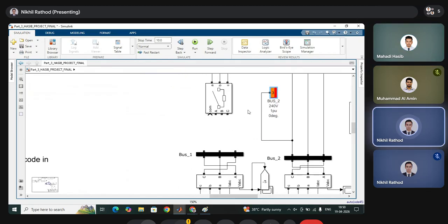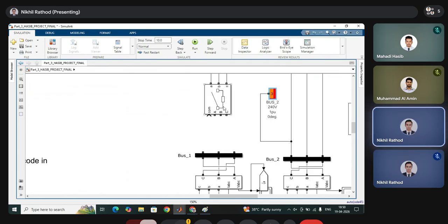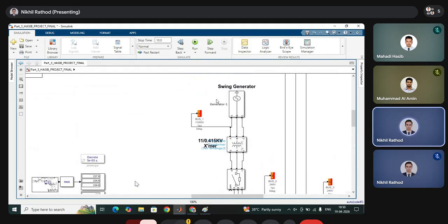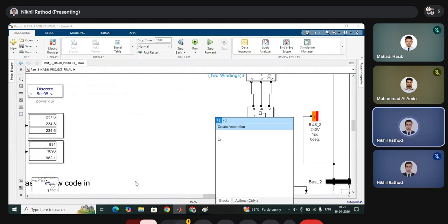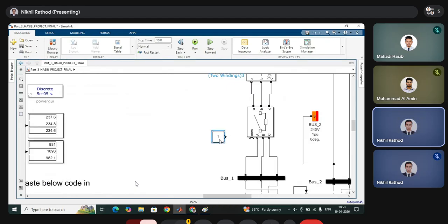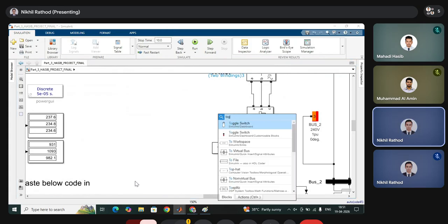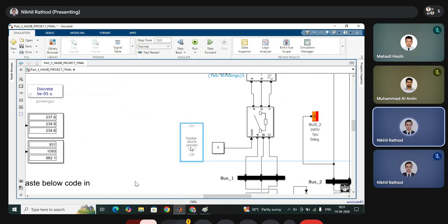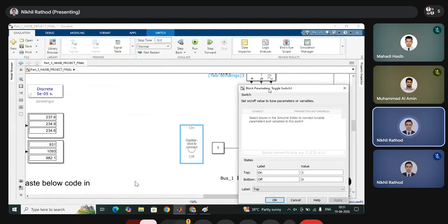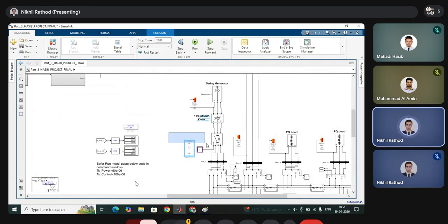But if you isolate this grid, because every generator is trying to, I can very frankly say, maintain frequency and all things through this source. It's a swing source. And if you directly isolate it, that may cause instability inside your system. And let's add one breaker at the PQ generator also, so you can see how the system behaves when one power plant is isolated.